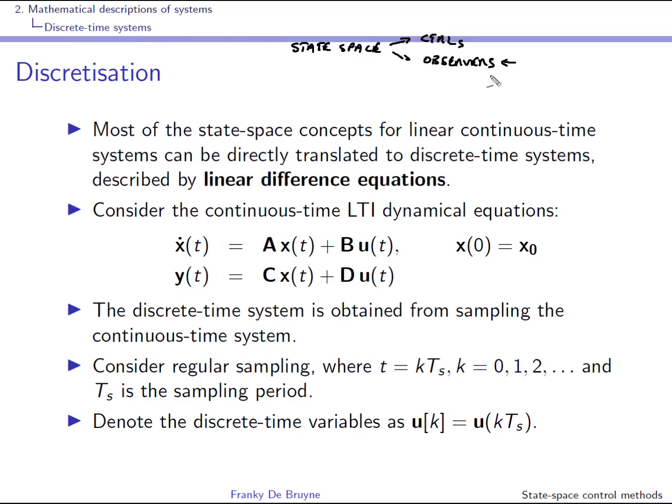But we will see in the course of digital control that this is not a very good strategy, because we do not take into account the zero order hold that is inherent to sampling in our design. So a better approach is to take the continuous time description and use a ZOH discretization method that will capture this zero order hold dynamics.